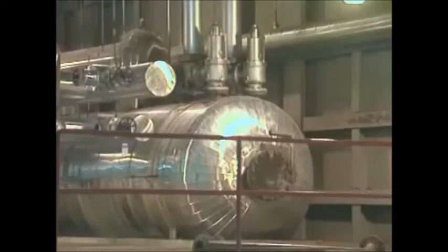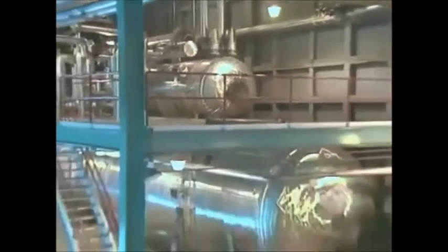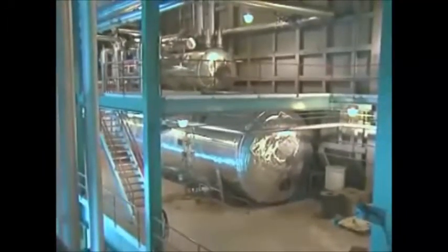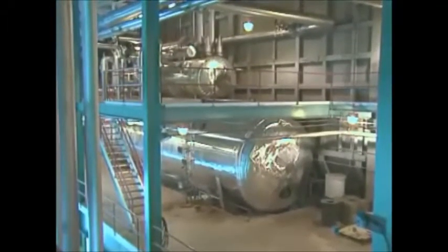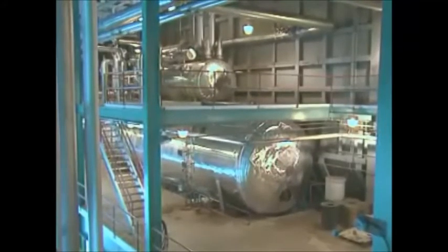The deaerator, which is an open heater, and the hot surge or deaerator storage tank that's associated with the deaerator must also be monitored when a condensate and feed water system is in operation. Check the level of water in the hot surge tank. There's usually a level sight glass on the tank that's used for this purpose.